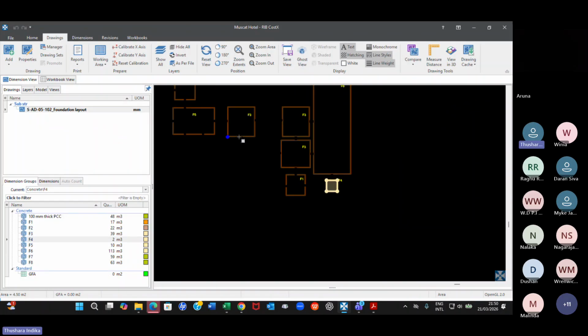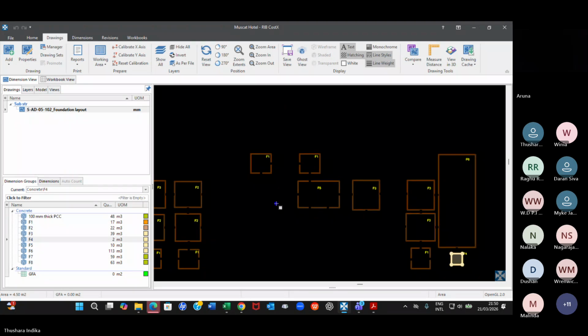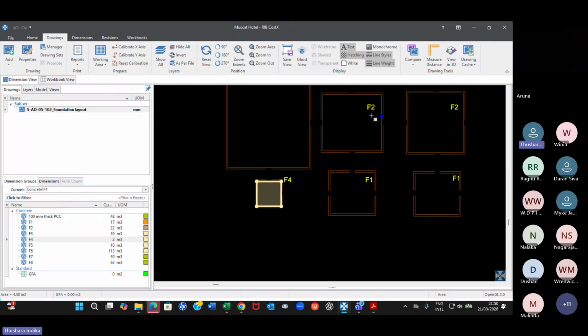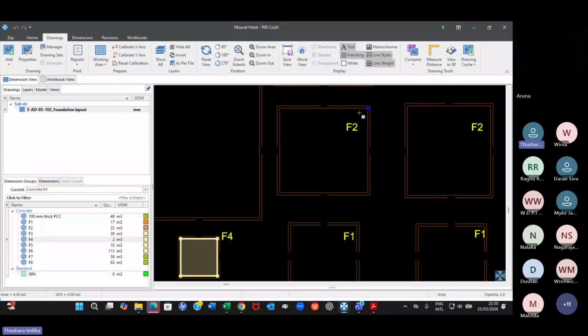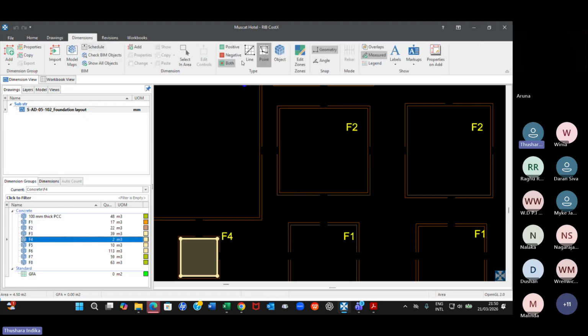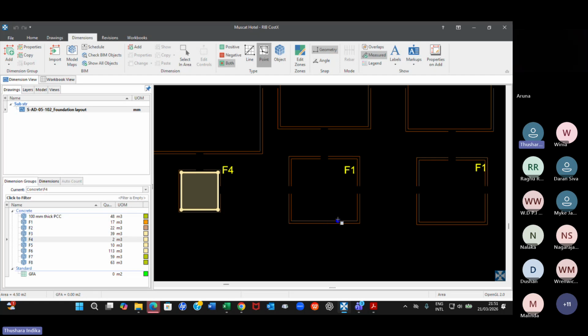So it's a practice. Just to conclude on that function, you can use the shift key with mouse to measure the area other than the line and point mode. But the problem is for that you need to have a kind of closed area if that is to work. You can use it for some unclosed area like this, but then you have to move your mouse a little bit here and there to select your proper area because the object is not closed.